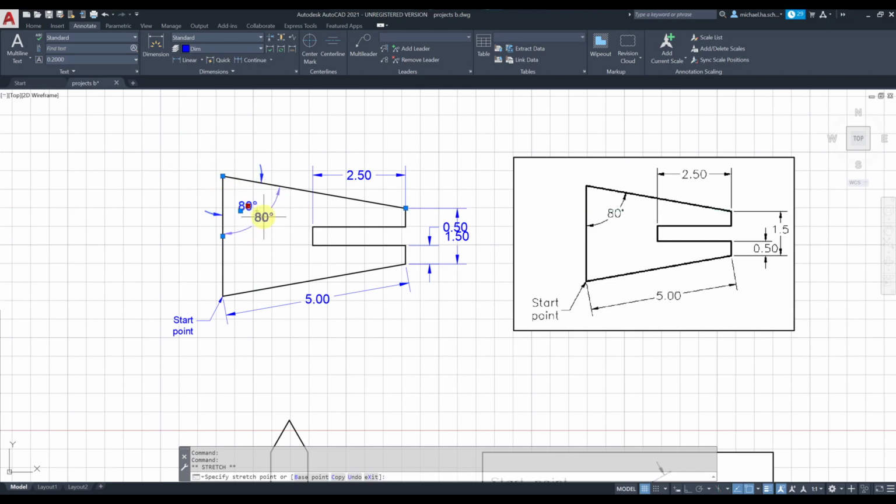Right now, as you see, it's snapping to some O snaps or object snaps. You can press F3 to turn them off. Okay, right now they're turned off and it doesn't snap anywhere. You can freely move it and place it anywhere you want. Again, grab it, move it to the middle, and escape. Gonna move these as well.